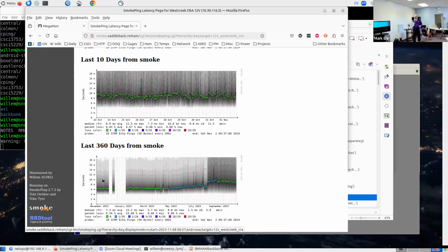But essentially, all of the electronics are just built into this little front here. It's got a metal reflector in the back to give you like a 25 dB gain on the antenna. But you basically just feed it through an Ethernet cable. You provide power over Ethernet at the far end with one of these injectors, and this will then plug into your device.